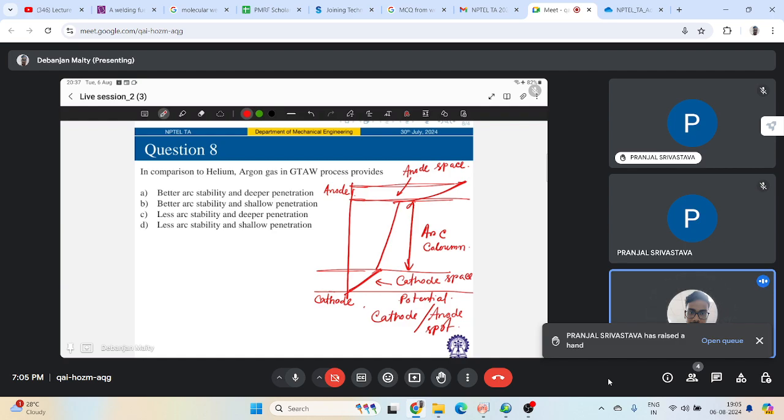Now, the cathode space is a gaseous region adjacent to the cathode spot, and it is also of smaller thickness compared to the arc column. Here in the cathode space we will have the positive space charge, which is easy to understand. Here a voltage drop is necessary because electrons have to be pulled across this region.